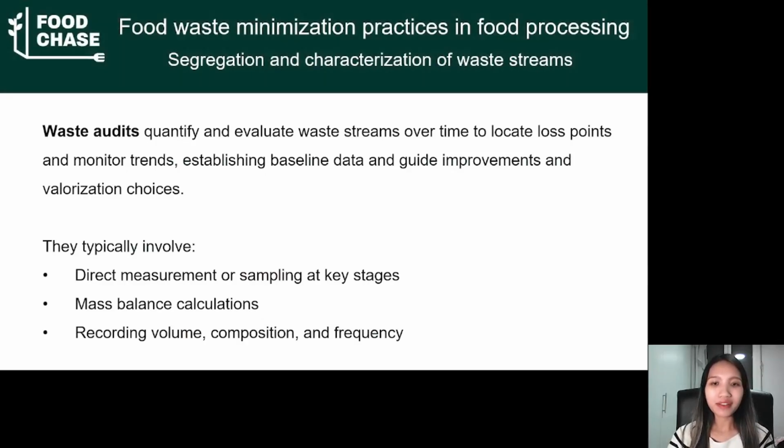A waste audit is a practice that can be done routinely in order to quantify and evaluate the waste stream over time, to locate loss points and monitor trends, establishing baseline data and guiding improvement and valorization choices. A typical waste audit can involve direct measurement or sampling at key stages where waste is generated, mass balance calculation to evaluate the quantity of waste, and recording volume, composition, and frequency to monitor the trends.